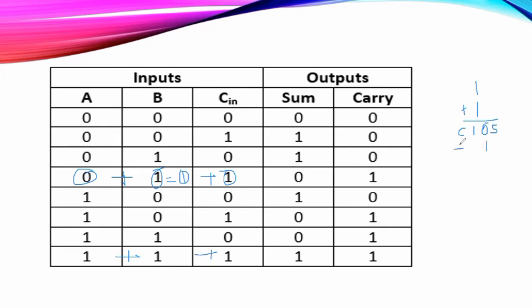And the carry will also be added to it. Okay. So 0 plus 1 is 1. And 1 will be taken as the output to the next one. So if you can see left hand side, it is carry, right hand side, it is sum. So sum is also 1, carry is also 1. Okay, this is how we will be performing the simple full adder.